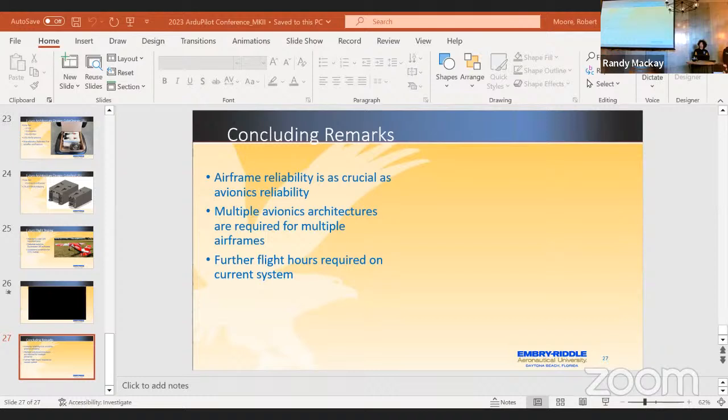However, what that relies on is, as you said, if you're in an auto mission, you've got both of these two autopilots running the same auto mission. However, the autopilot that's not controlled may think it didn't quite reach the waypoint yet, so it may not trigger the next waypoint. So that's where the overriding thing needs to actually pass that information. State changes, waypoint. That's right.